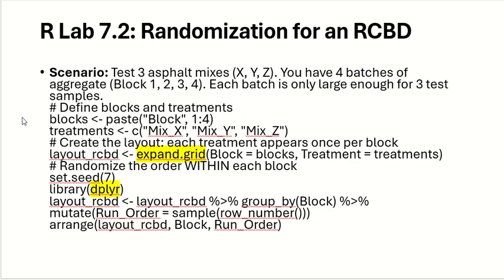Just on this note, what property of the aggregates do we use for design? Size. So we do the sieve analysis or size distribution and we say, okay, now it's good for design. But that doesn't mean the other things related to the aggregates are not affecting the mix.